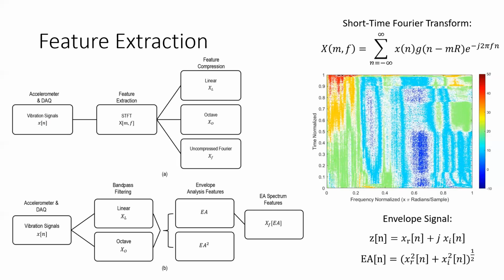The transform involves calculating the windowed DFT of time samples, with each window overlapping the previous by a factor of 75%. The average value of these complex features is calculated for each time sample, which produces a spectral feature vector consisting of 512 points. These points are separated at intervals of 25 Hz and represent the spectral amplitudes over a range of 0 to Nyquist frequency of 12.8 kHz.